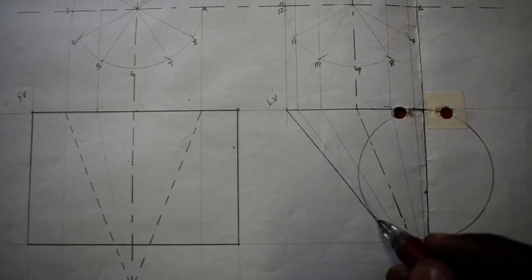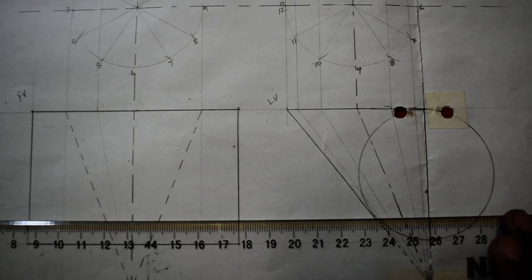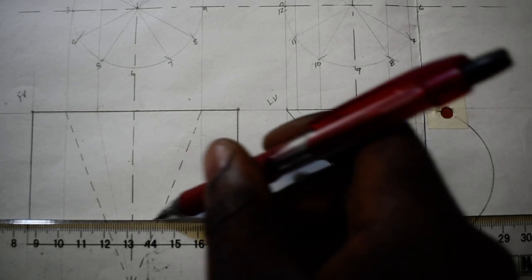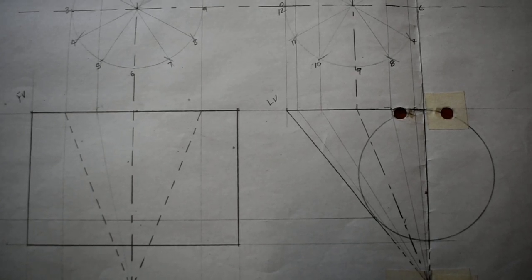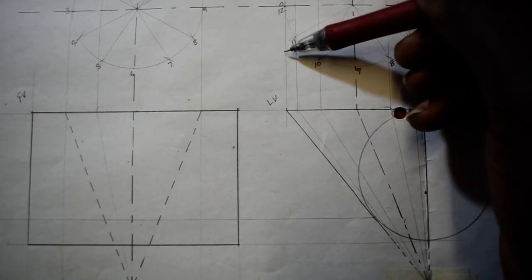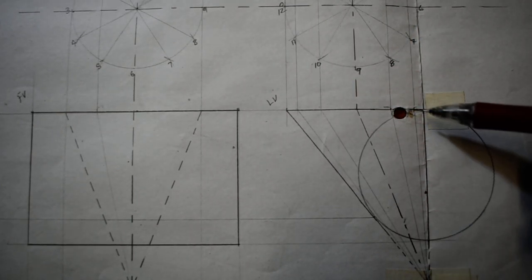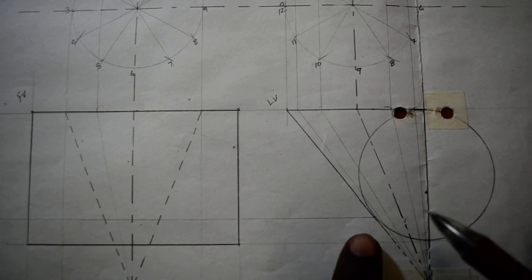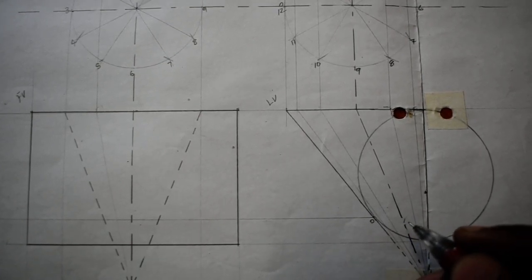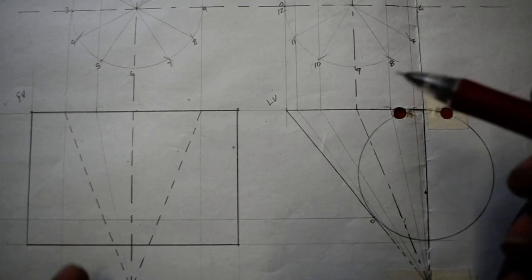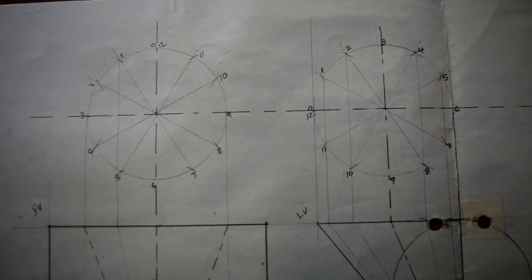But once it touches the main pipe, you're going to take it horizontally towards your front view. You understand? So this is point 0. There it goes. Once it gets there, take it to your what? To your apex point. Once it touches the main pipe, you have a point which is point 0. So you're going to take it horizontally. This point 0 is going to intersect with the 0 of my auxiliary front view, which is this one.